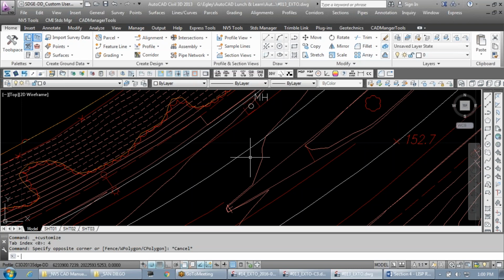But then when I go and XREF that EXUT into my plan sheet, I don't want those colors. I want it all to be screened back, right? Or maybe a little darker on the sewer, depending on what I'm doing. This is where layer states can come into play.